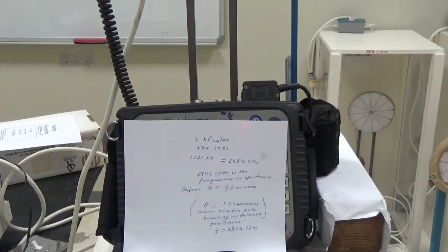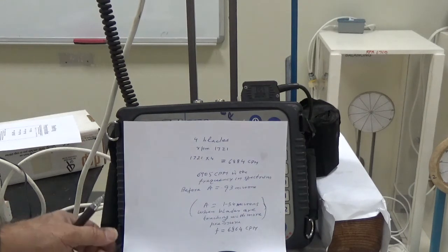But in both the cases, the amplitude which I have taken is at the frequency which is blade pass frequency. So I will measure amplitude at the blade pass frequency. So the amplitude at blade pass frequency is telling me how much the blades are touching the cover plate. If the cover plate touches with more pressure, the amplitude will increase. Okay. So let me do now the third experiment. Now I will increase the pressure more and let us see again.